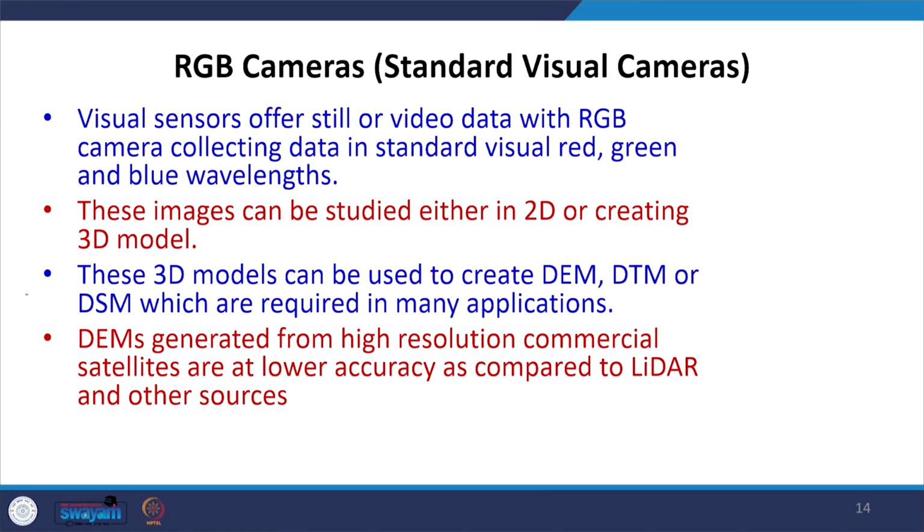And these 3D models can later be used to create either a digital elevation model, digital terrain model or digital surface model, which is the basic requirement in many applications, particularly when we are doing town planning or working on some hydrological model. The DEMs which we generate from high resolution commercial satellites are at lower accuracy as compared to LiDAR and other sources.